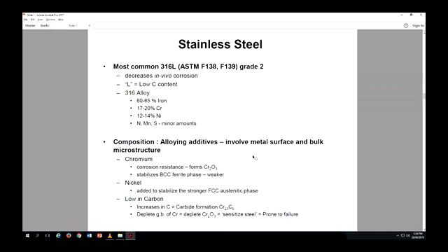But what happens is the FCC has a lot more concentration, so it's a very dense crystal structure as opposed to BCC. With BCC, you will have a lot of empty space, basically, that can sometimes be filled with carbon or other material that you don't want, or the atoms can slip on each other in the metal. So it's not as strong as FCC, right? So this is a different structure.